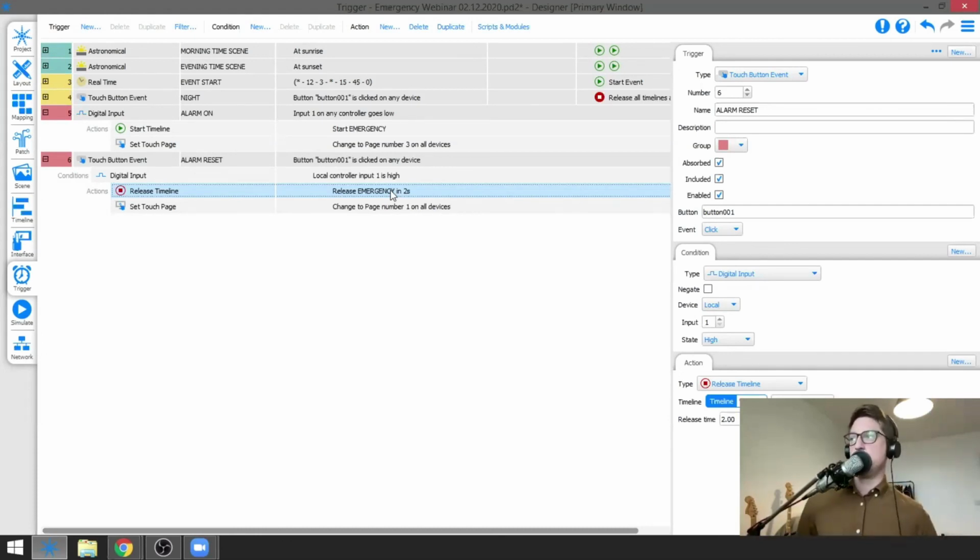Obviously, Pharos is a lighting control system, and I think it's really, really important to point out that you should build a system around your lighting control system. So, as Baz has already mentioned, a UPS that powers the systems is definitely the best way to go when looking at this type of thing.